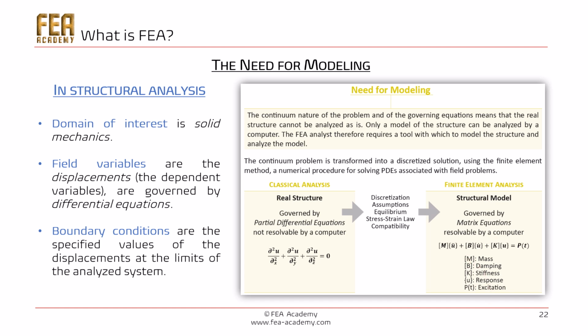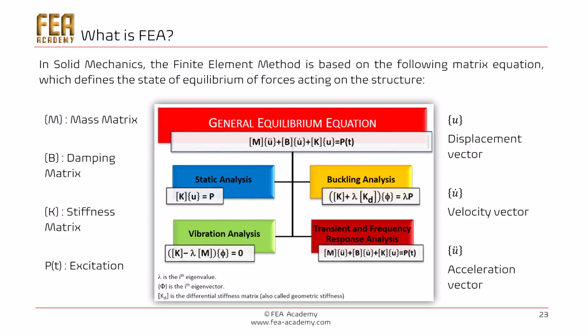And this structural model is governed by matrix equations. The transformation from PDE to matrix equations has been done using the finite element method. So we obtain a matrix equation that the computer can solve. So in solid mechanics, the finite element method is based on this matrix equation, which defines the state of equilibrium of forces acting on the structure.